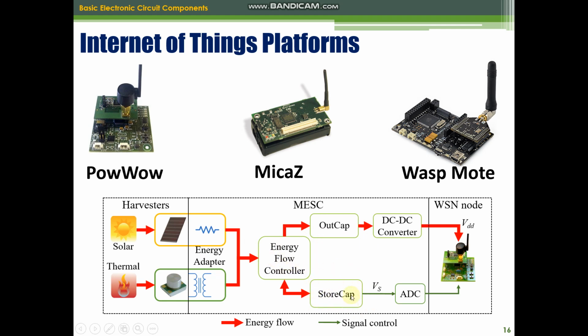We charge the energy storage very frequently. So if we use the battery here, the lifetime of the system is very short because we can charge it only around 500 times. If we can combine with the supercapacitors, the lifetime of the device can be increased much longer.